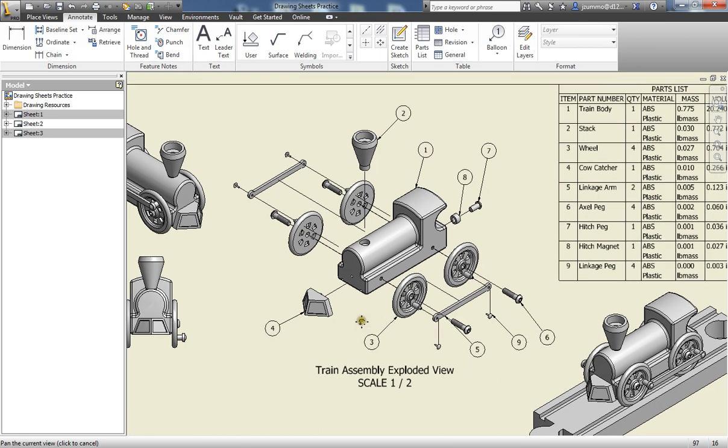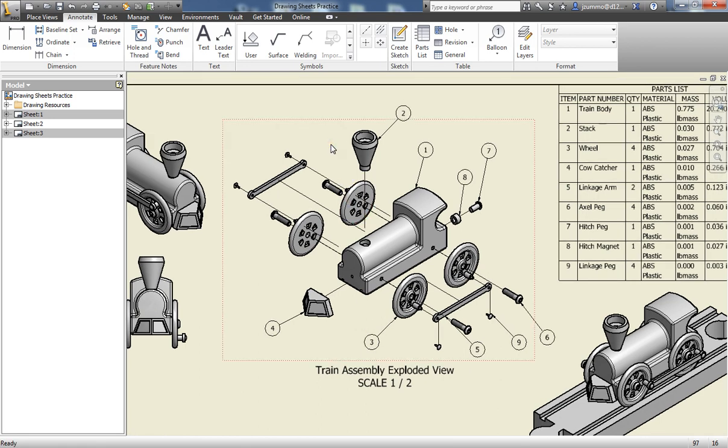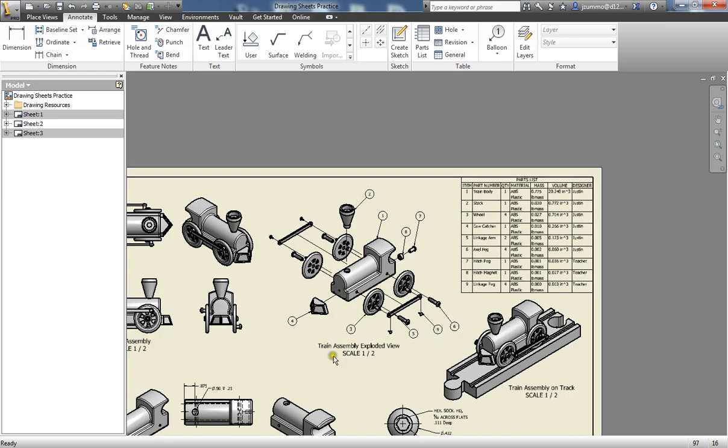To get this view here, you're going to need to create a presentation IPN file. Of course, you need to make sure that you have white space in between every single one of your parts. If you do not have white space, you need to go back to your presentation file and increase the tweaks that you had set on each individual part.